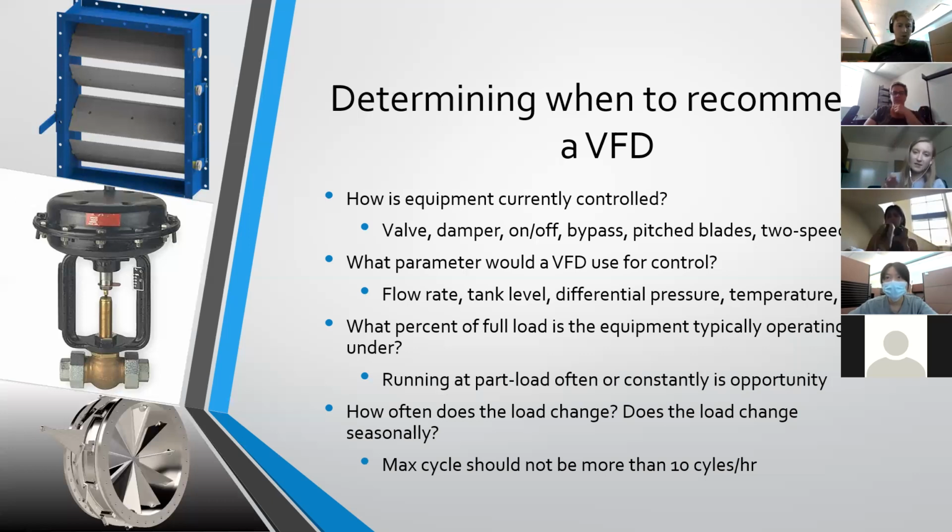If we have time to go into pump curves, then we can start talking about your static head pressure versus your dynamic pressure in your system, which all has to do with what's happening around the pump, not just at the pump itself. But yeah, differential pressure is basically discharge minus suction pressure.